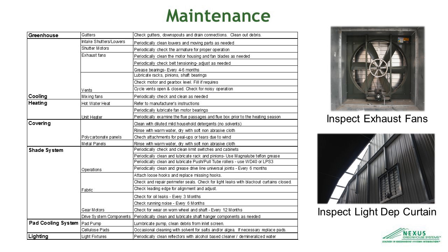Your pad cooling system, depending on where you're located in the country, you might use your pad cooling system year-round. You might use it seasonally. If you're using it seasonally before turning it on every year, typically you have it locked out during parts of the year where it's really cold because you don't want any freezing to take place on the pad cooling system.